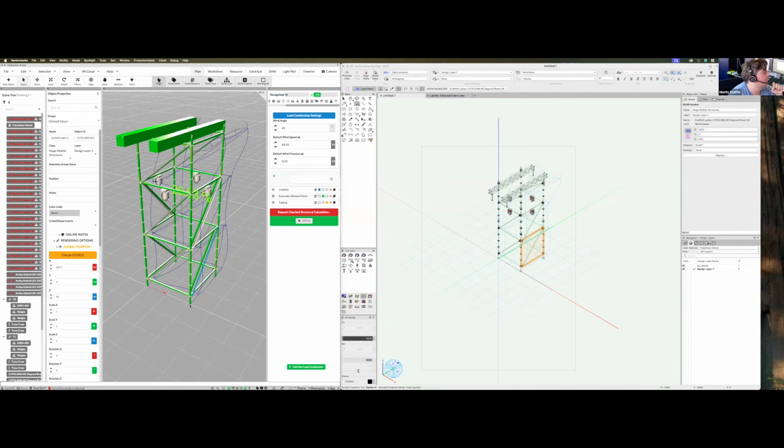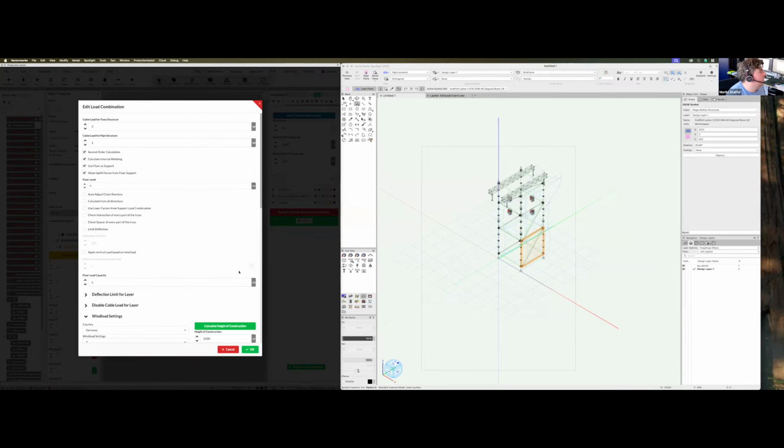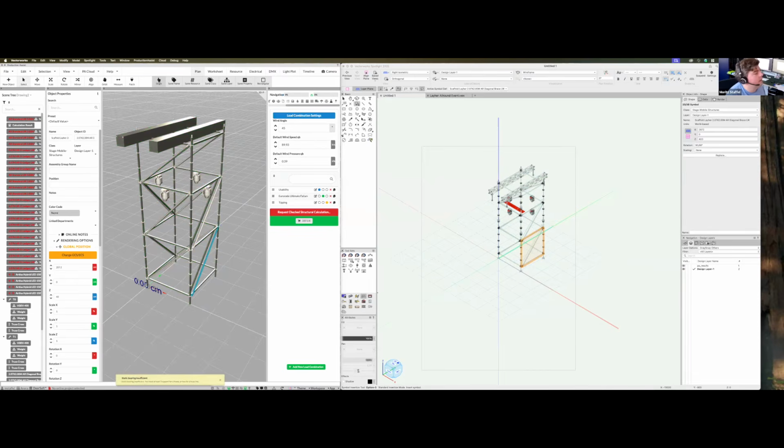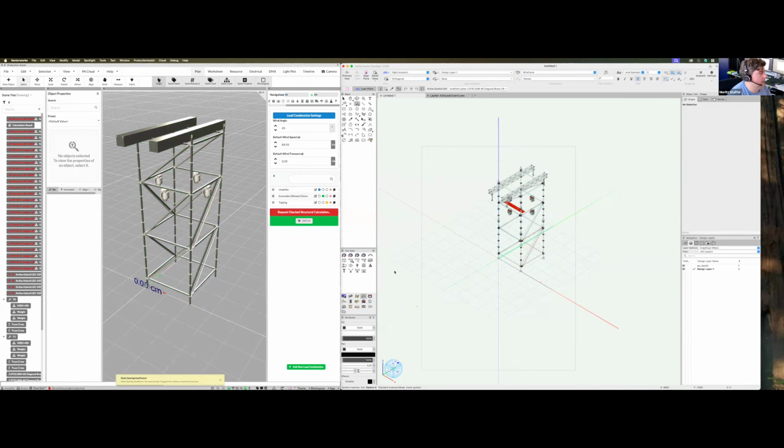to calculate this. So what we currently did till now was actually that we used the floor as kind of a support. The next step, what we want to do is actually calculate the ballast that we need for this thing. And for calculating the ballast in here, what you need is real supports for this. So it's not that challenging. So what we do is we disable the floor in here, the supports with this in here. And wait, now it becomes gray, says it can't be calculated.